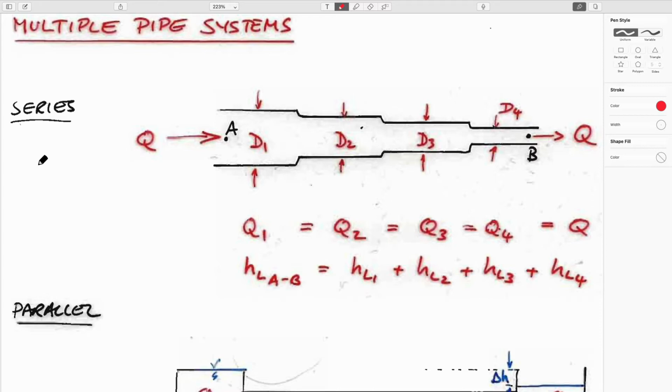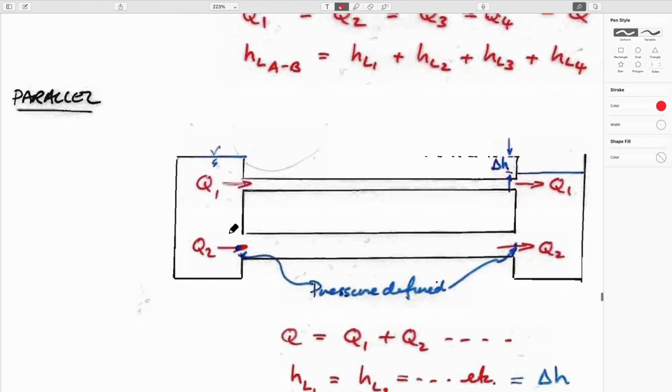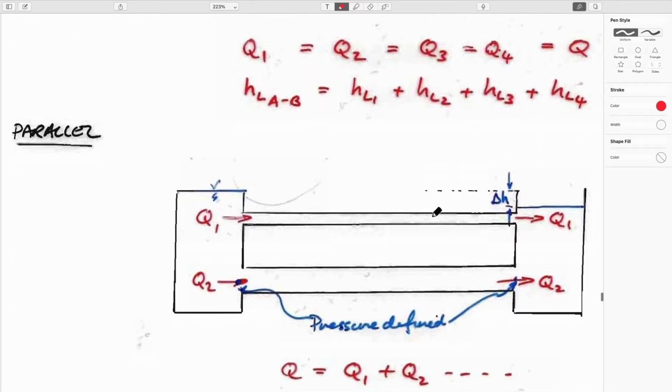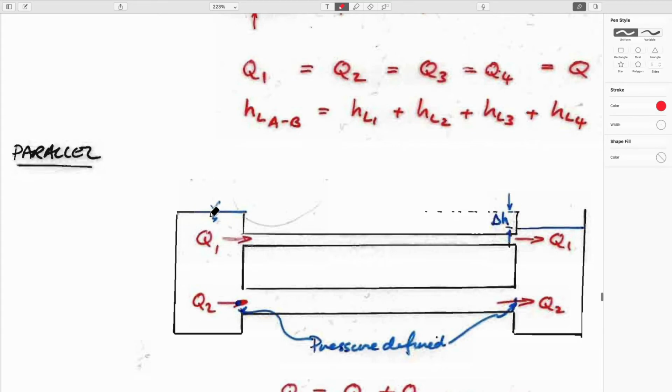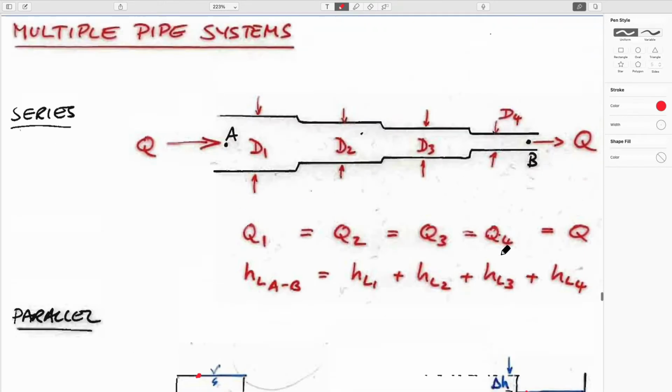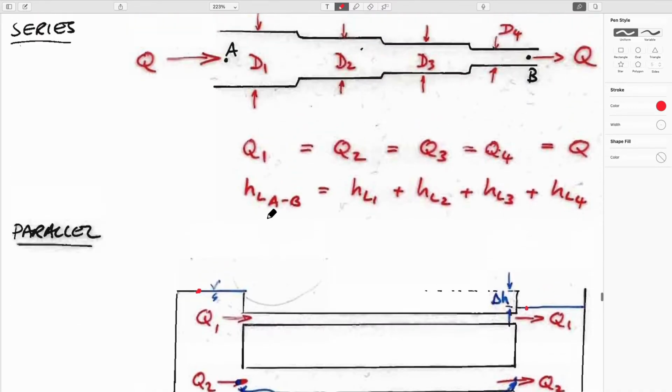If we write it between an upstream and a downstream reservoir like this, we're really defining the head loss in terms of some head loss between upstream and downstream. With the big reservoir assumptions, this head loss would be a delta Z between Z1 and Z2. And so that would be implicit in this single pipe connecting these 2 reservoirs.